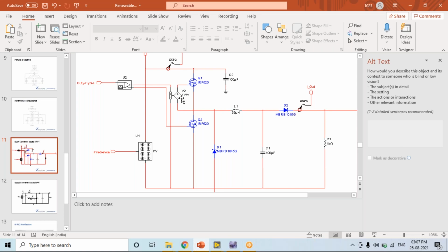More importantly, the switching frequency of the boost converter is going to be very instrumental in selecting those. We need to make sure that the switching frequency of the buck converter or boost converter is not going to go beyond RF. If you go beyond RF, it should be a power MOSFET which is capable of switching at RF frequencies, so we need to be very careful in that. And of course, we have a lot of web-based tools which, when we enter certain parameters, are going to suggest an appropriate buck converter.